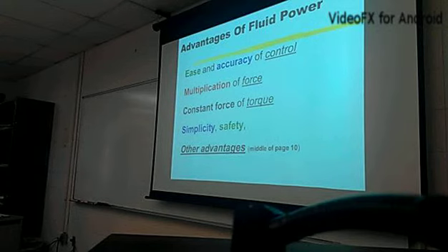You can't instantly reverse electric motors all that well. But you can with hydraulics. Now you may shear some keyways when you try to pull this off, but there are certain applications designed in hydraulics that you just about can't pull off with an electric motor because of the electromotive slip. Okay, so there is going to be that little gap. Let me give you an example of that.